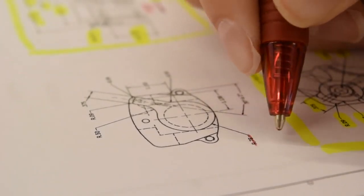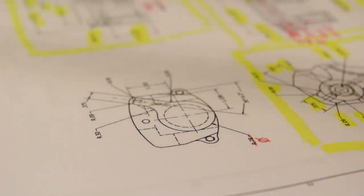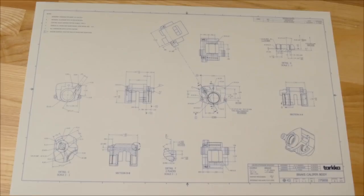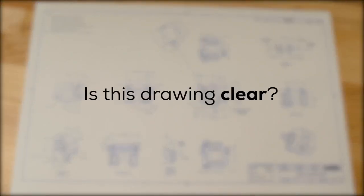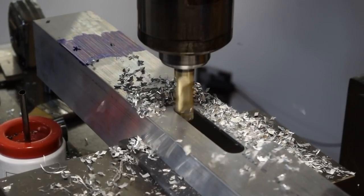We've given a lot of little details in this video, but we want to emphasize that your primary objective is to make drawings that are totally clear. We've posted a checklist to our website to help when reviewing a CAD drawing, but you should always do a final check by asking yourself, can a total stranger that knows nothing about my company or product look at this drawing and make exactly what I want without needing to call me?